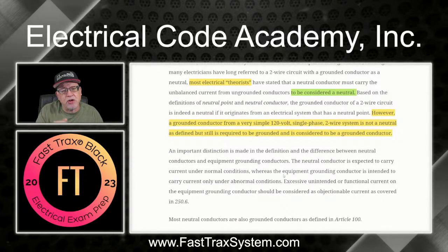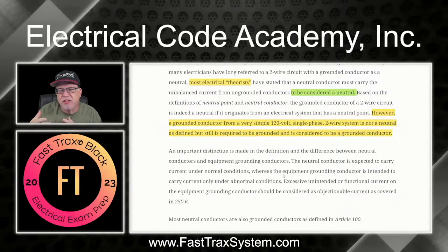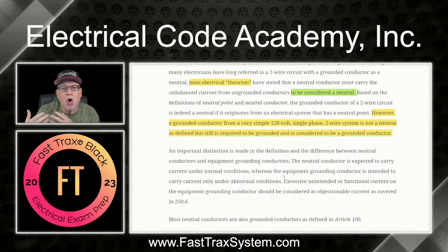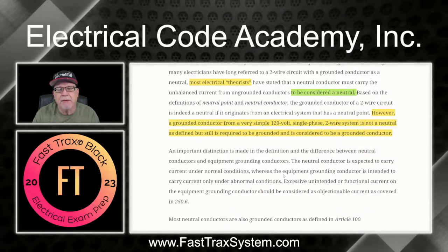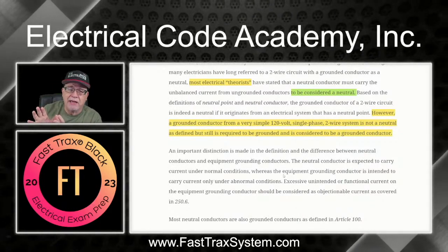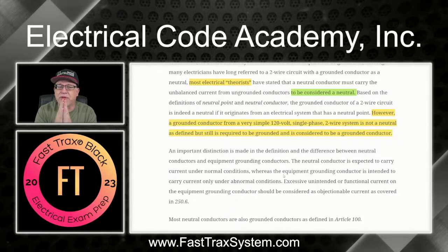And again, while we talked about it earlier, improper connections of case to neutrals downstream create objectionable currents, and it can put potential current on metal components, especially if you make that connection and for some reason you have a weak neutral connection and you lose that connection. Now you've got that return current traveling on metal parts, and that becomes a hazard. So there are many reasons why we have to distinctively understand the difference between equipment grounds and neutrals. Even though they connect together on the same bus in your service, once we go downstream, they must be separated, okay?